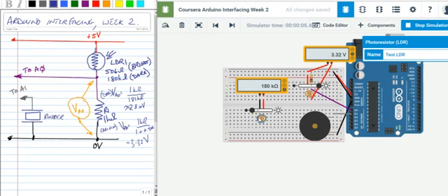If we take a look, I've just rigged up one of these over here on the board just to measure the resistance. When we are fully dark, it simulates 180 kilo ohms, and when we are fully light, it simulates to 506 ohms. I've written them down over here. We're adjusting this voltage, which goes between 28 millivolts up to 3.32 volts. We can see the 3.32 volts there now.